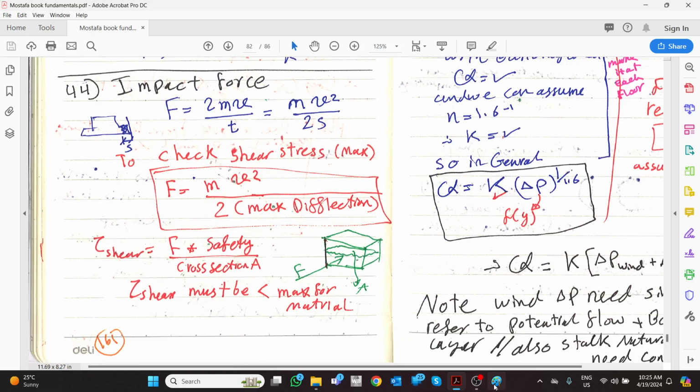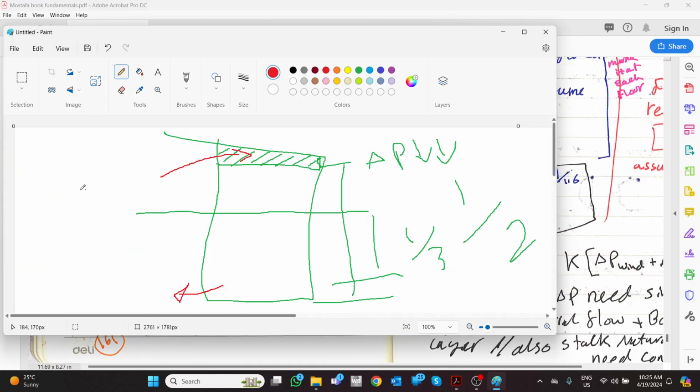Of course, when it is above the natural plane, if it is hot outside and cold inside, it will always flow in. But here there is too much, here little, so it will skip here. So when you are doing your heat load calculation, you need to put an infiltration rate different for each floor, or you can even put it at the maximum for your safe side. So in supervising, we put an infiltration rate, okay?